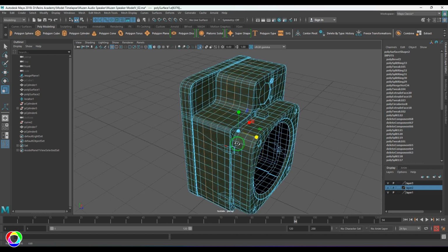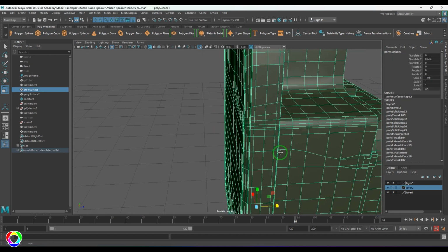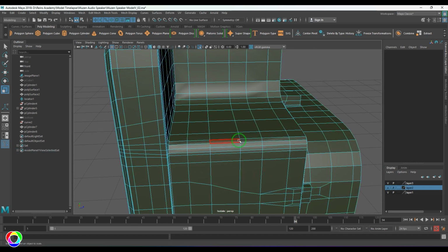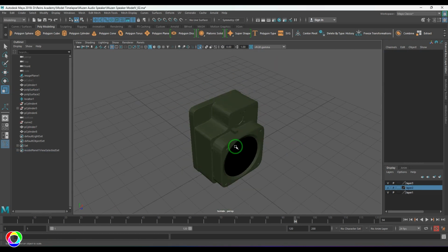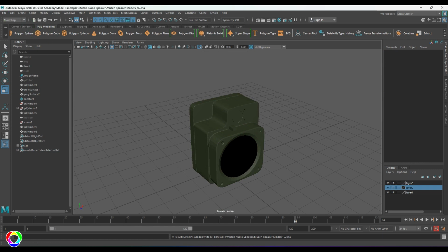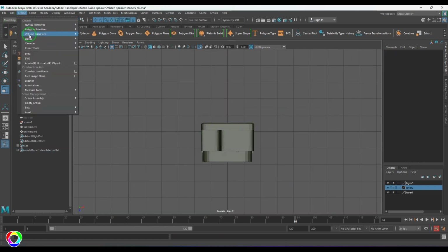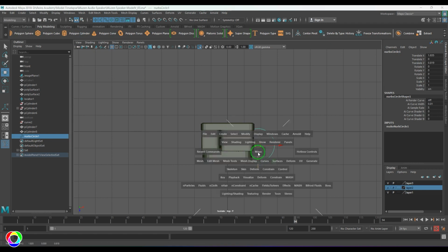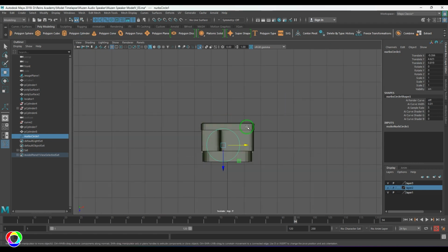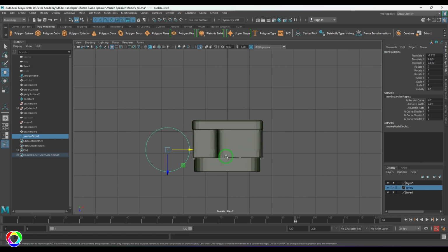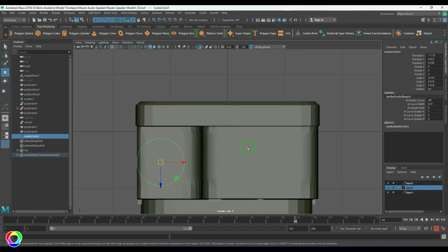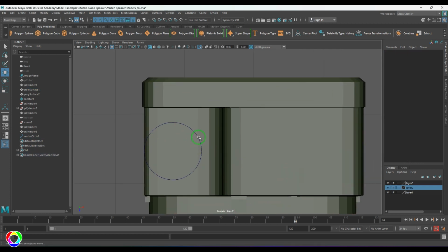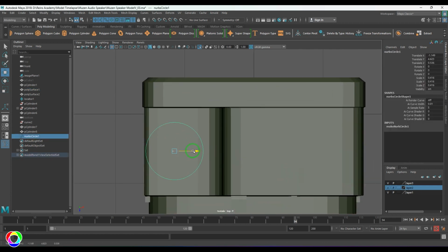I'm actually selecting those faces and extruding them, but before going into that, I need that nice circular cut, which is precisely on the edge. That's some important detail. So let me take a circle and then put it on top here, which should generally pass through the edge actually.